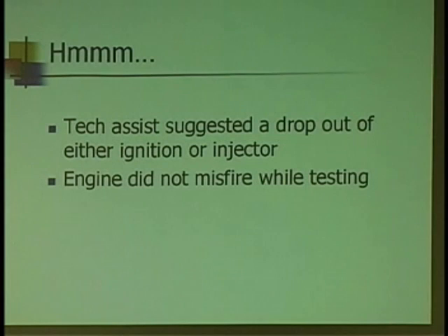Back they came again. Now they're working with Identifix and the tech line at Identifix. And they're saying, okay, well, if mechanically the engine's good, then there must be an issue with either the injector dropping out or the coil dropping out. How are you going to test that? Can you swap coils? Are they coil on plug? Yeah. Swap coils. Yeah, but what if it was the driver's side of the circuit, not the coil?